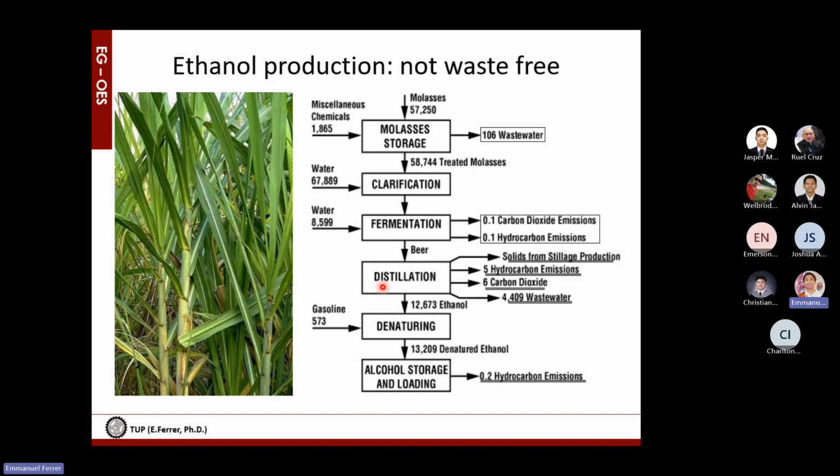Because we have what is called the azeotropic point, where water no longer wants to separate from alcohol. So there is always an affinity between water and alcohol. We use chemical treatment to remove the remaining moisture. Now, denaturing. Ethanol is consumable, so it's more expensive because of a sort of food tax. To reduce the cost, we denature it. We add other forms of alcohol which are toxic.